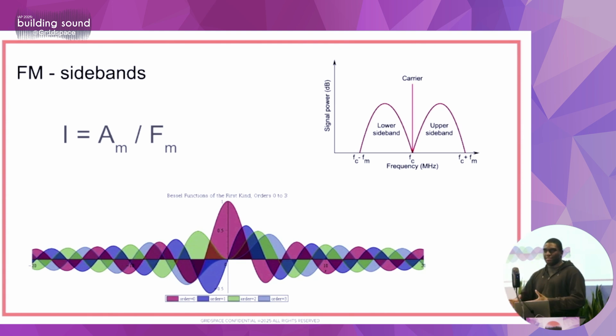So in FM synths, you can actually generate harmonic and inharmonic sounds using the relation between these two frequencies, where if they have a rational relation to each other, then you'll end up with a relatively harmonic sound, even if it's not necessarily consonant, but that's more subjective. And if the relation between the two frequencies is irrational, then you will end up with a purely inharmonic sound.